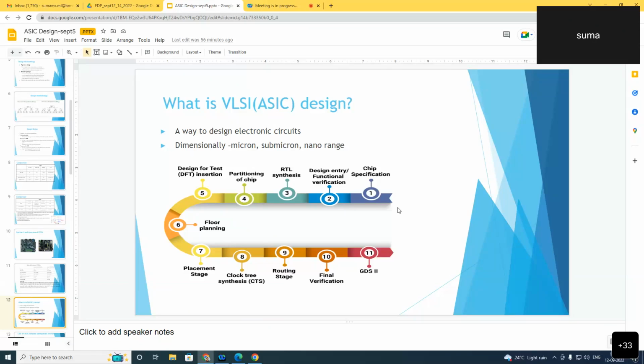We will see all this one by one, and when we are doing this, we will see the clock frequency is also increasing with a continuous increase in the number of transistors on chip. And when we are implementing low power techniques, especially for these designs, we have to see that these techniques are being implemented across all levels of abstraction, that is from system level to the device level.